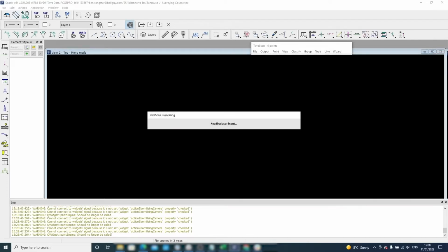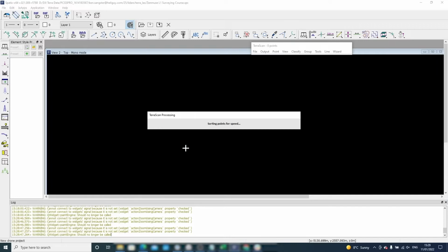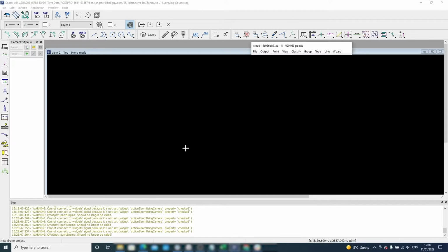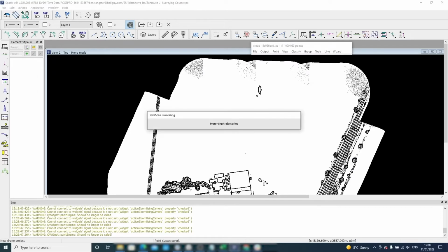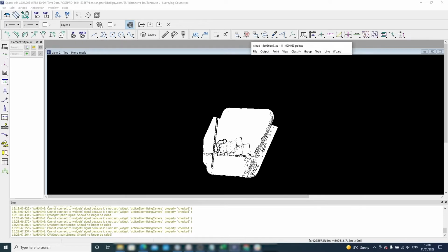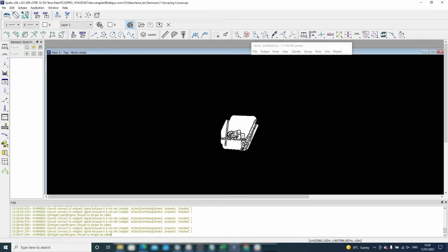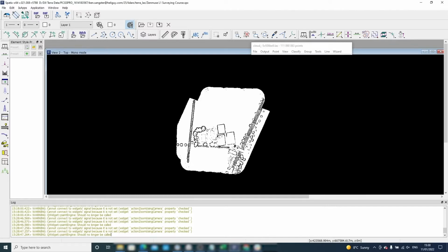If your dataset was particularly large and Terra has exported more than one LAS file for your dataset, simply rerun the Start New Drone Project window to load more LAS files into your SPATIX project. Providing that the trajectory information is correct, the point cloud should align automatically if you have exported more than one LAS file from DJI Terra.